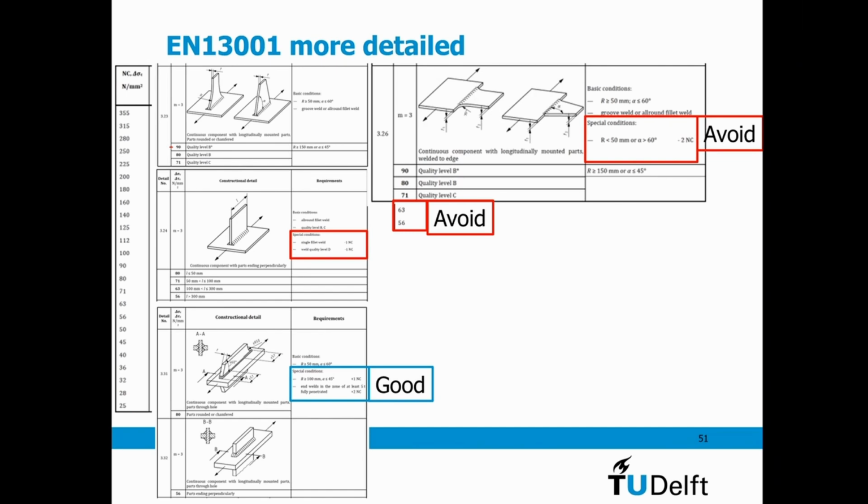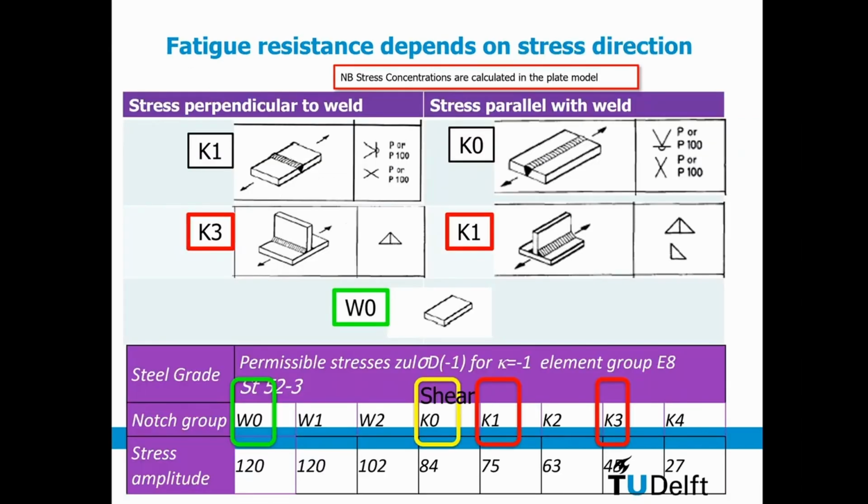Yeah, and you should also read these standards not as a cookbook. Okay, this is my allowable stress, and let's see what we get. You can also, in the design phase, take into account, okay, if I want to be able to design up to a certain stress level, I need to have a quality at least this. And so if you read it that way, then this becomes an indication book on how to make details.